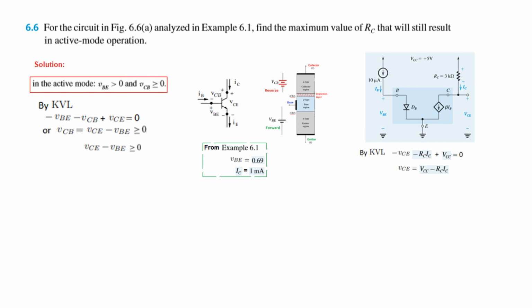So the battery is actually connected here. So this is the KVL, and from here we can find VCE to be VCC minus ICRC. This you have to remember, we'll be using this term very frequently, that VCE is VCC minus the voltage drop across RC. That is another way of finding this.